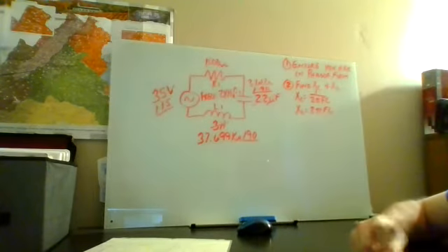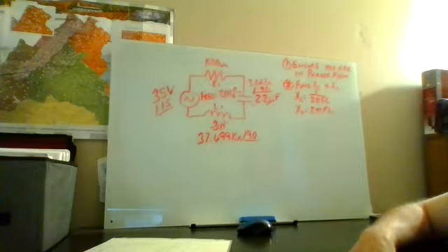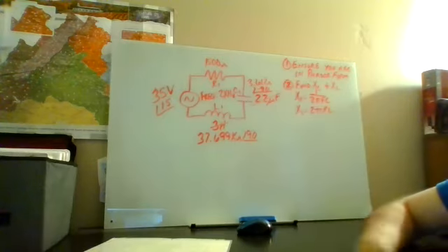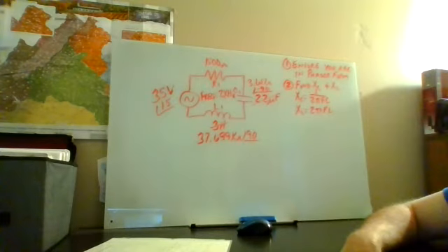Well, I just did the X of C. Yes. And I got 3.617 at an angle of 90. How'd you get an angle of 90? I did 2 pi times 2,000 times 22 exponent negative 6 angle negative 90. Nope, you don't put the angle on there now. You don't put the angle on until you get your ohms. Oh, okay. So once you get your ohms, then you put the angle of negative 90 on there.